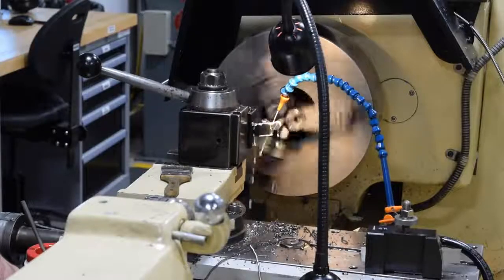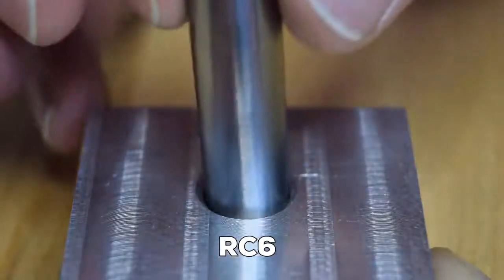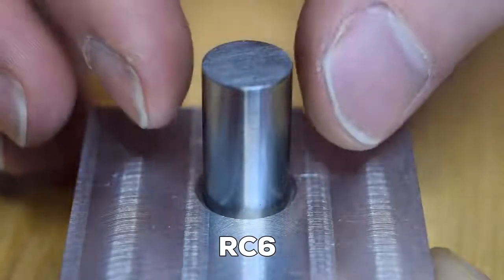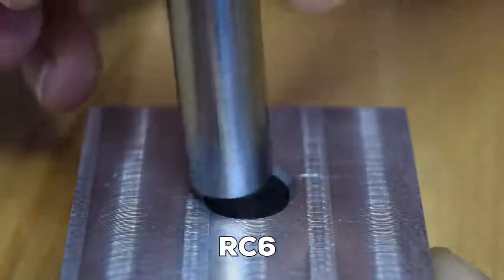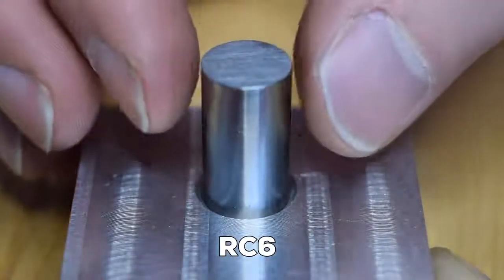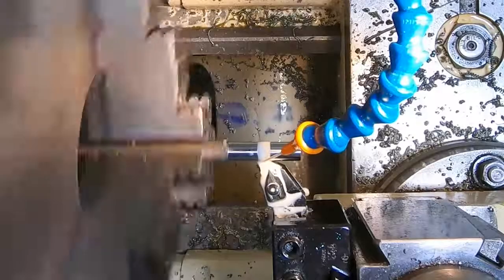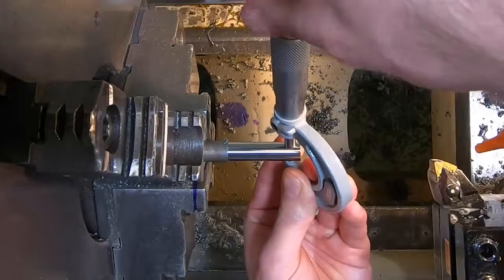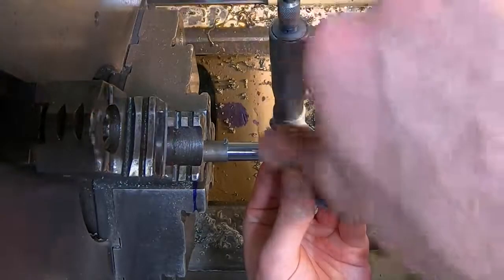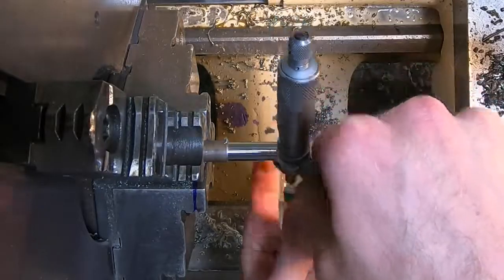Depending on the size, this is probably about the tightest shaft tolerance that you can expect to hit consistently by turning. This is the fit to use when you need two parts to align to each other, but some clearance is acceptable. This is the tightest fit that can be readily achieved with normal manufacturing processes and without undue effort. For the rest of the fits in this video, we're going to have to work a bit to hit the tolerances, and you're going to want to be absolutely sure you need this in your design, because you'll be paying for that care and attention.